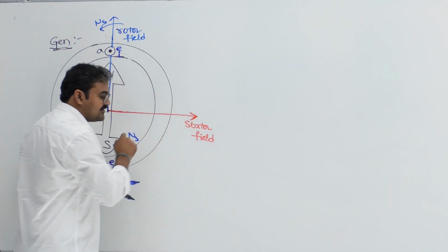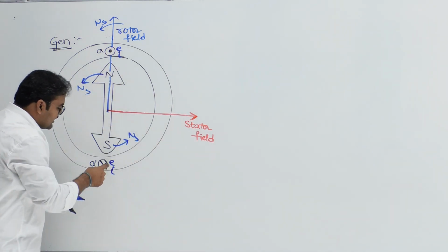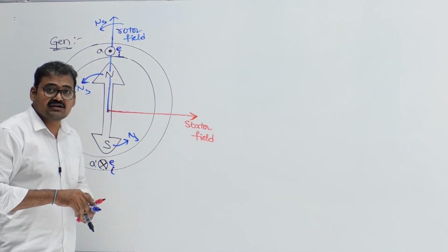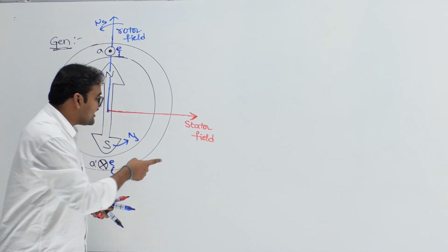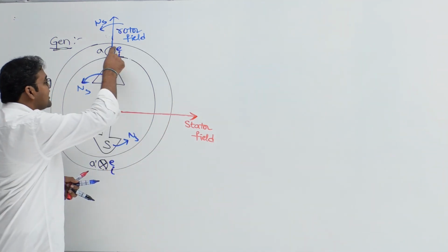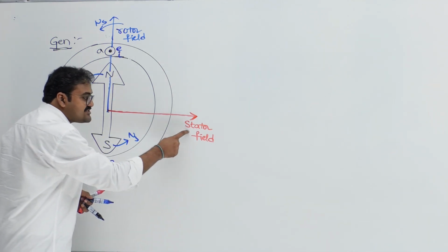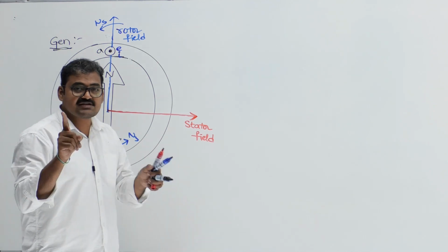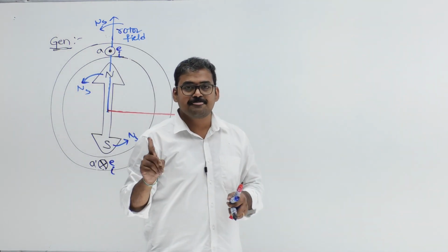Coming to stator field, tell me stator conductors are rotating or stationary? Stationary. If stator conductors are stationary, don't say stator field is also stationary. That is wrong. Even though stator conductors are stationary, stator field will rotate definitely. Why? Because we discussed in the entire induction machine course.